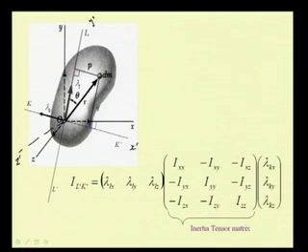set of principal axes. So, if we know the second moment of this mass with respect to the original axis, that is x, y, z, then it is possible to determine this inertia tensor matrix for an arbitrary orthogonal set of axes, that is O x prime, O y prime, O z prime passing through the same point.